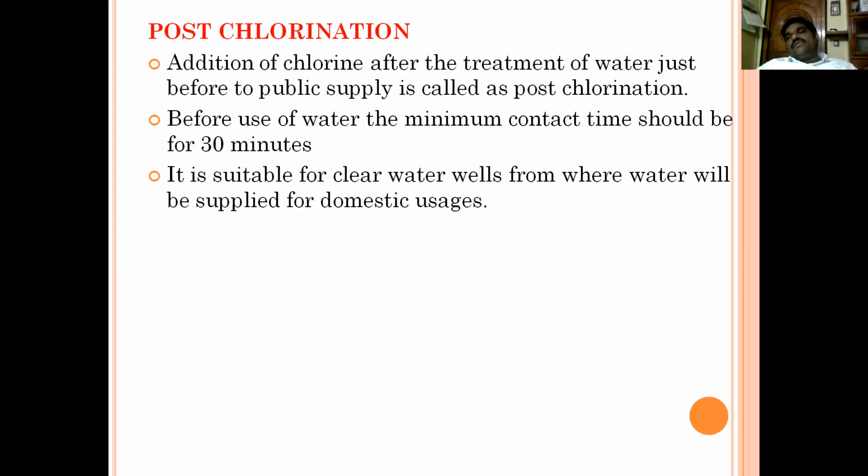Next one is post-chlorination. Addition of chlorine after the treatment of water, just before public supply, is called post-chlorination. Before use of water, the minimum contact time should be 30 minutes, and it is suitable for all clean water wells from where water will be supplied to domestic users.